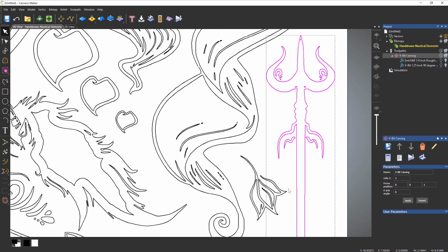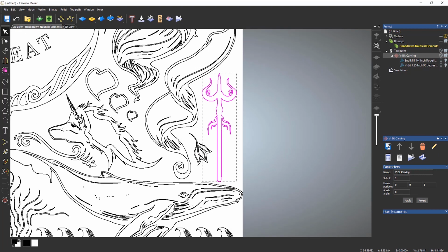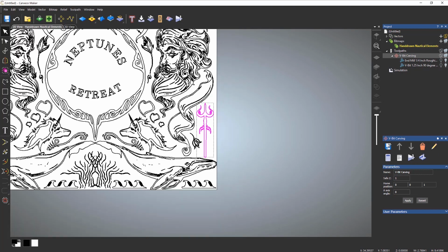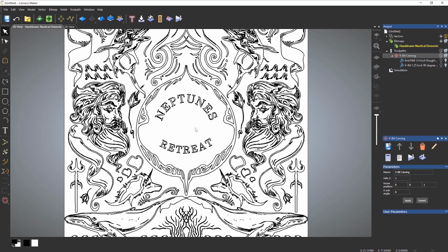Now, if you happen to select something else, just press Shift on the keyboard and then left click to deselect it. Okay. Now what I'm going to do is to copy this. So if I move over like so, just select it again, and if I hover over it, I can actually move that around if I left click. And what I'm going to do is press Control down whilst doing this, and I'm just going to drop it anywhere. Okay, so that's created a copy.